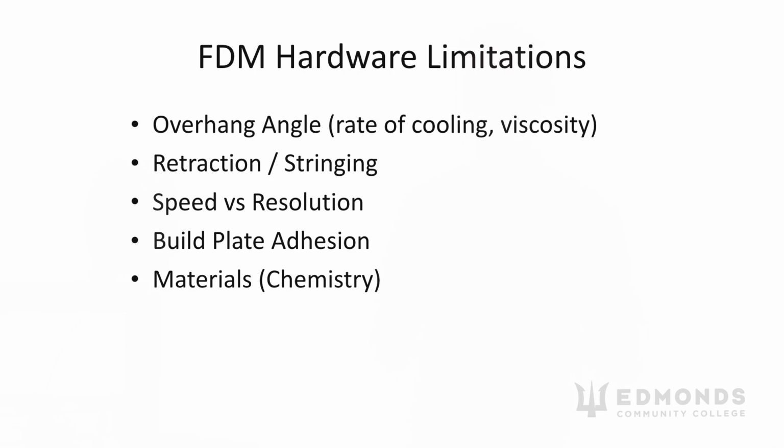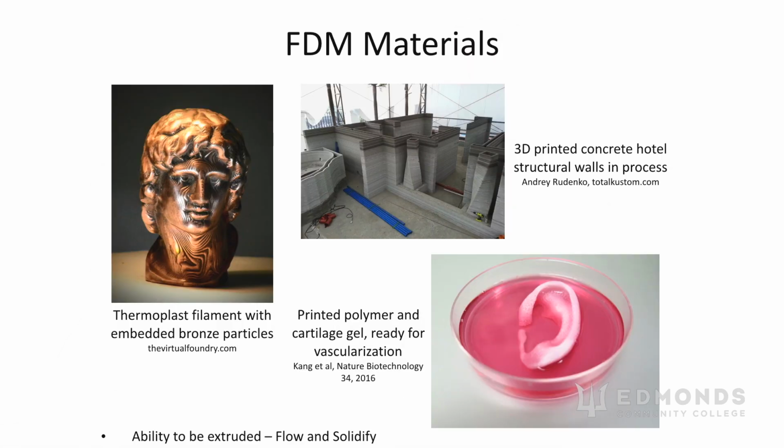We can solve some of those problems by using thermoplast fills. We could embed particles in this plastic. Of course, then we would be adding something else to the mix. We'd have to change some of our heating properties. We might have to make our nozzle more durable as a result, especially if we're going to put glass or carbon fibers into our plastic.